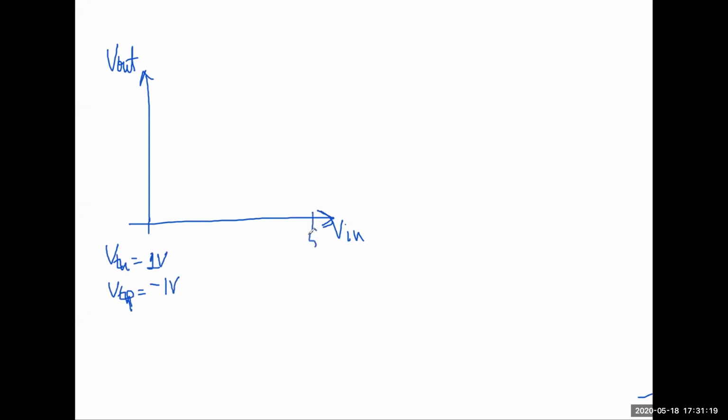Let's say it's a 5 volt supply, so in CMOS, this one remains on till 1 volt and this will be off from 4 volt, right? So this is ground and this is VDD. And if your sizes are such that, let's say Kn is 2 times Kp, well, actually I should write it as mu n and mu p.